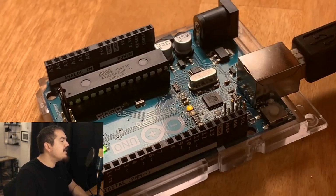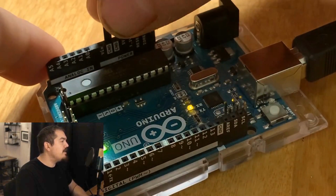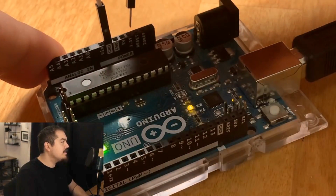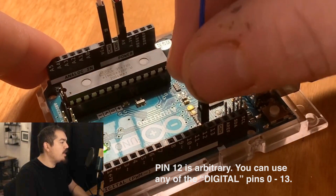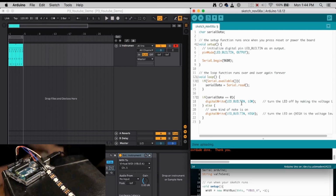So now we can connect our pins to the board. Ground goes into any of the ground ports. Our power goes into our 5 volts, and I'm going to use pin 12 for our data here. So let's get Arduino powering these Neopixels.